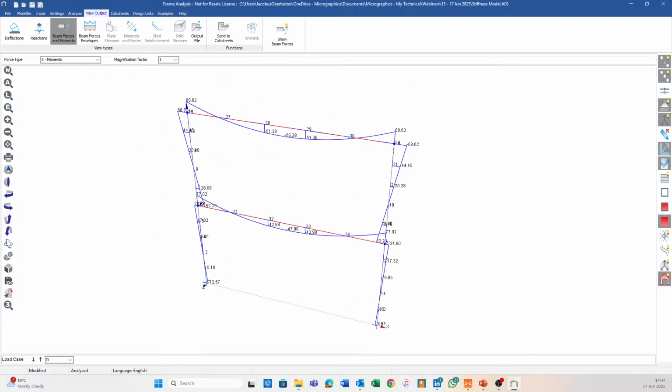All right, so that is our webinar done and dusted. If you have questions, you're welcome to ask. Otherwise, you can always get hold of me via email. Send me a mail. If you want the model, send it to me and I'll send it through. Even if you just want to see how you model stiffness within frame, or how you model springs. In this case, we've actually had a real life application where they had a type of rubberized connection, like an elastomeric connection, and they needed to simulate that stiffness in their global model. So we've actually had something like this happen before, where it was necessary to simulate the model just like this and actually check what is the effect on the bending moments and deflection in the model.